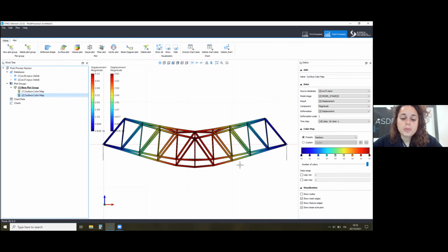With the geometric transformation, I can study the contribution of the geometric nonlinearity, but it does not mean that I will have large displacement, even if it's used with large displacement problems. So the difference is actually that I can reach larger displacement exactly because I use this kind of geometric transformation that takes into account how my structure geometrically works.